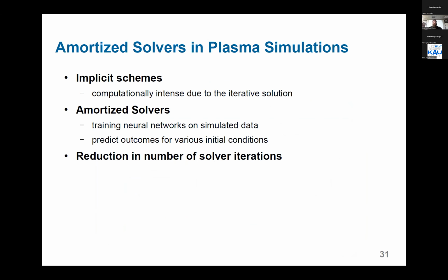What you want to use it for is then, let's say, to enhance your field solver. In case you're using so-called implicit schemes, then for each of your field integration time steps, you don't solve the single time step delta t with a single iteration of calculating your differential equation. You usually use some iterative scheme, which uses some preconditioning of those matrices, and that's extremely computationally intense, because you might need several thousands of iterations to solve a single time step.